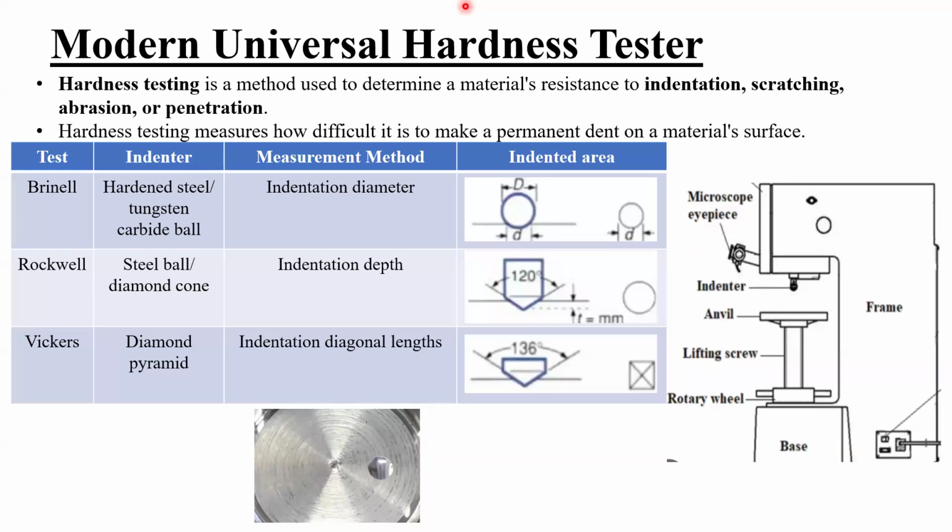But with rubber materials it is not preferred to use this hardness tester, because if you get a dent of 0.25 when the particular force is applied, once you take the indenter out of the material, it might go back to 0.22. That might affect your tolerance level as well.